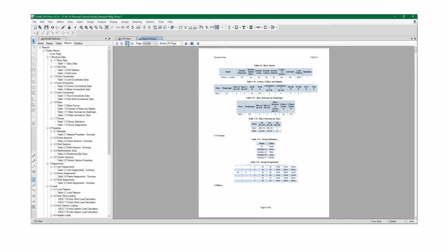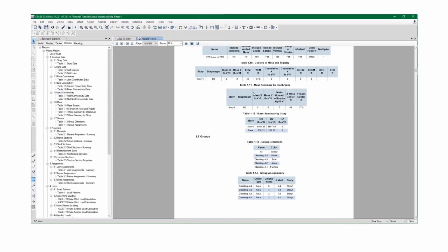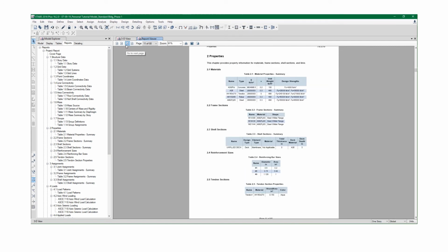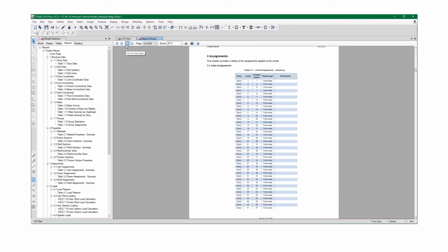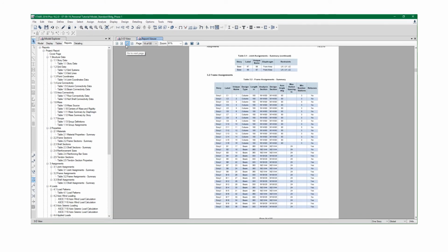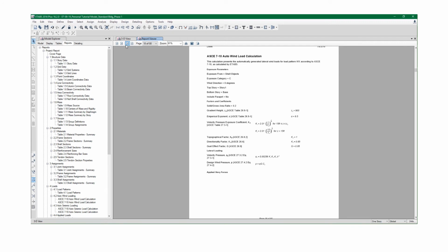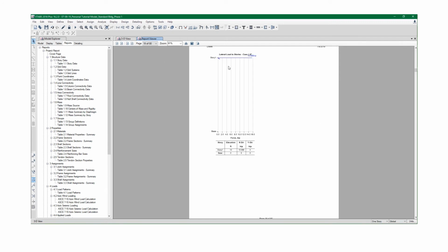It's all kinds of information: beam connectivity, story data, diaphragm masses, like I said, your diaphragm center points, XM and YM. See it right here. Very good information. Some of it is not related, but it's necessary. Auto wind calculations for your wind. You can see 15.5 or 15.6 kips were created for the X direction.